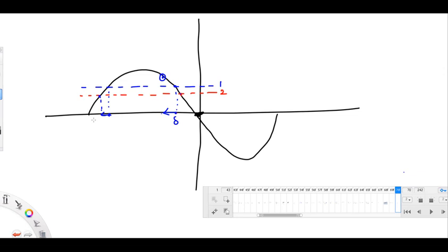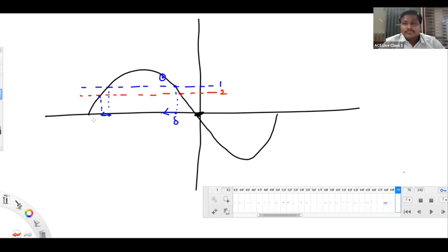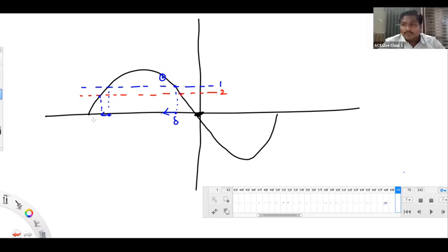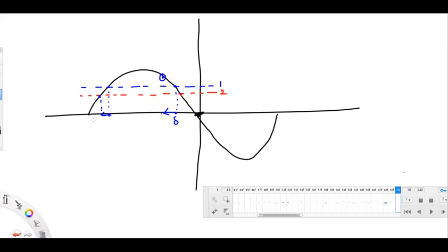Sir, that is when we are calculating self-inductance, L_AA, L_AB, L_AC, for line A. We are doing 0.2 ln 1 by D_AB. That's the mutual inductance between A and B. Inside the ln term, what unit will be placed, meter or kilometer?